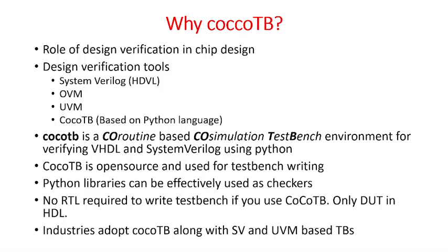So coming to the CocoTB part, right? It's basically an open source platform based on Python. And there are SystemVerilog and OVM, one of the oldest verification methodologies, and then UVM is being very widely used. Most industries use UVM, the universal verification methodology. It uses a general schematic structure where you have a generator and driver, right? And then the stimulus generation process, and the generated stimulus goes to the DUT, and then the DUT outputs the data, and the checker verifies whether the DUT output matches the specification or not.